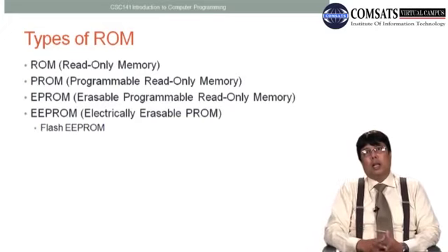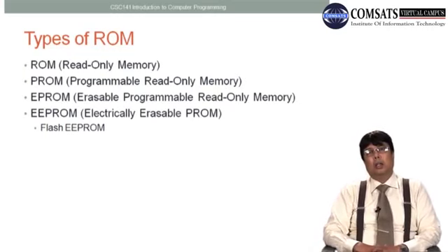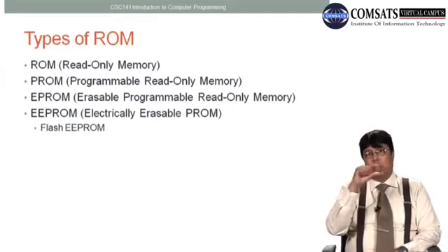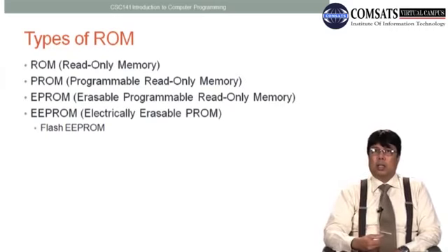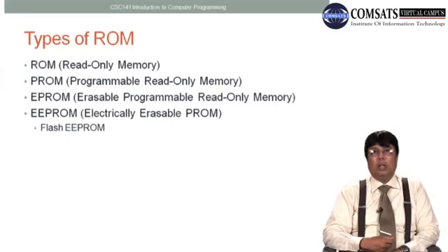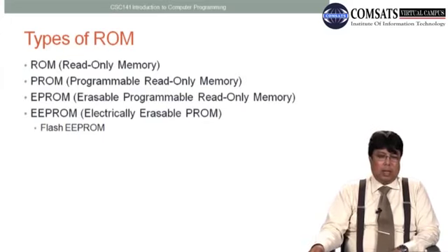We used to erase EPROMs in old days with the help of a tube light. We used to stick this EPROM with tape to the rod of the tube light. Usually an ultraviolet box takes 10 to 15 minutes to erase the data, whereas if you stick it to the rod of the tube light, it will take 1 day to erase the data. But it has almost been obsoleted now.